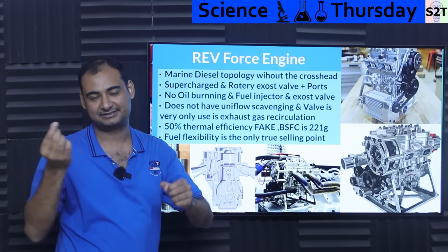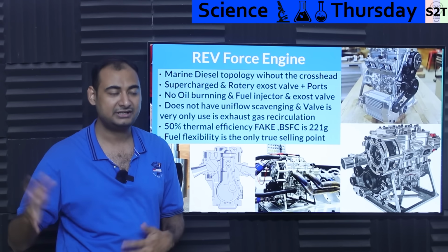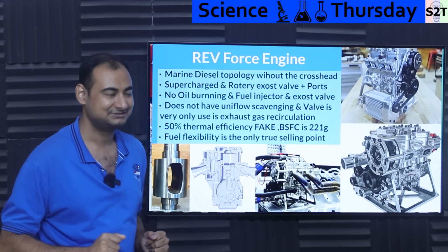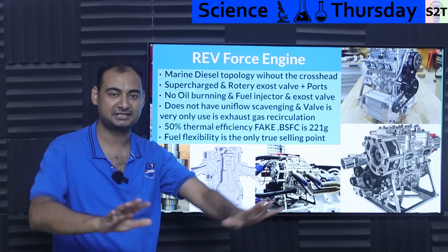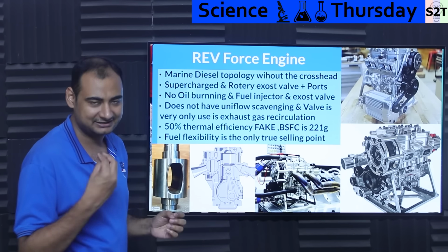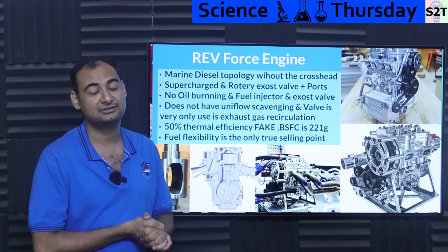Basically, the crankcase has a system which we call crankcase ventilation. We dump it into oil. Now, why don't we vent it outside? You can, but you will not meet regulation now. So we have to vent it inside. It goes through the engine, then through the catalytic converter. The catalytic converter breaks it down. Cool, awesome. But again, that means you have gunk going to the poppet valves on the intake.